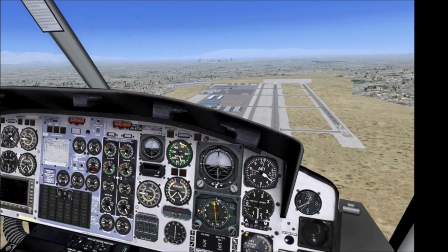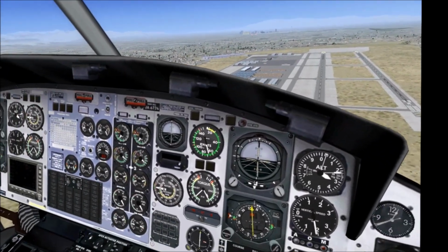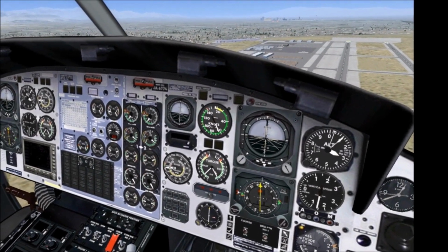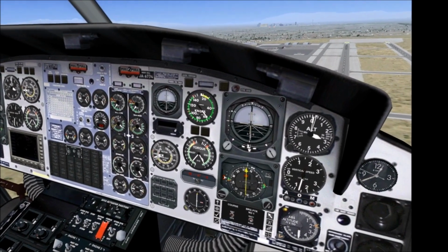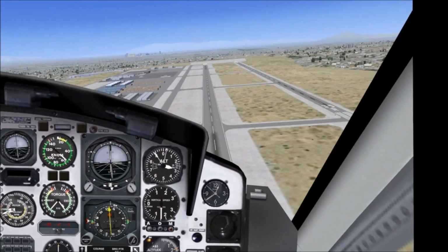Okay, so we got some odd behavior there. So looks like we started to get a needle split. And then, okay, so I had the throttle idle and the needles married. I'm going to crack the throttle open just a little bit, and it looks like we're getting a needle split then. But it's a reluctant needle split.